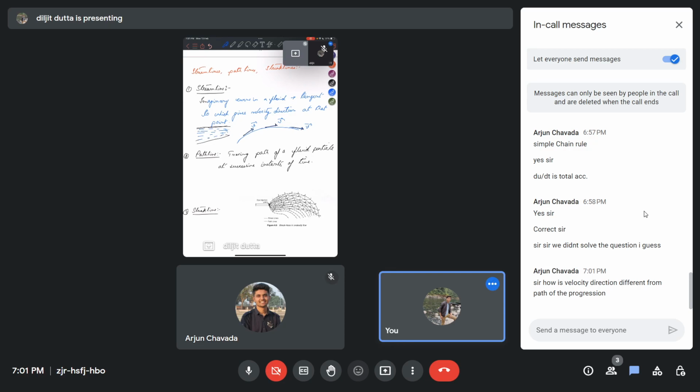This whole fluid will have different streamlines, and each streamline corresponds to the velocity at that point and the velocity direction along the fluid flow. When you are taking the path line, it is like tracing only one particle.